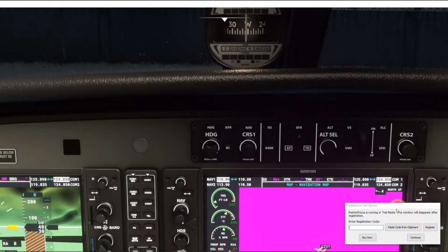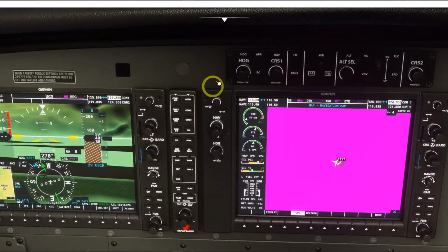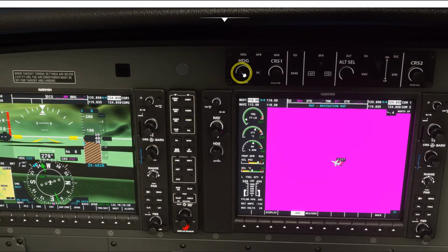let's go to Autopilot. The Autopilot here is actually quite simple to understand. It's self-explanatory. There's a heading bug here, the navigation or the course here, the Autopilot button here. It turns on the flight director automatically, or you can just select the flight director on its own. If you have set a GPS flight, you would select NAV and it will fly the whole plan on the GPS.